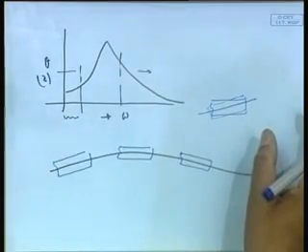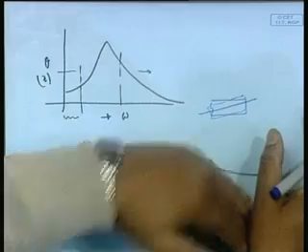Since the frequency is low, the period is high, so I have enough time for the body to adjust itself to the local slope, because only in the local slope does my dynamic moment become 0. After all, for hydrostatic equilibrium, the total hydrostatic force must be 0 and the moment must be 0. In this case, that happens. So this is why it follows that.